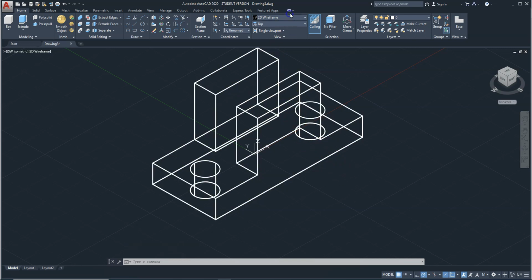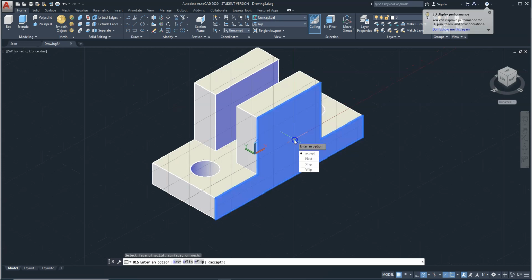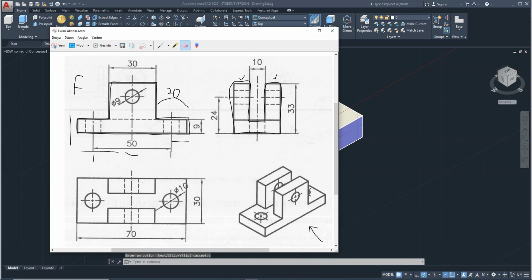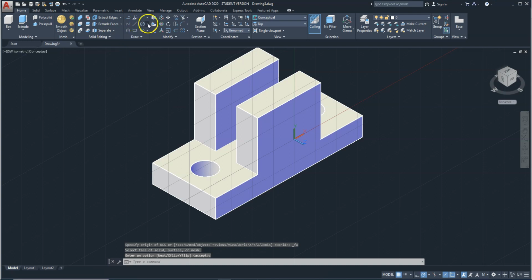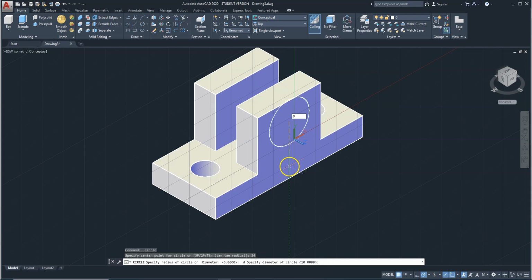And now look at the model again to check, and finally, as you know, I select this face command and select this face to open a hole here, and look at the dimensions, 9mm and 24mm from the bottom. Select center diameter, find the midpoint, yes, go up for 20mm and 9mm.